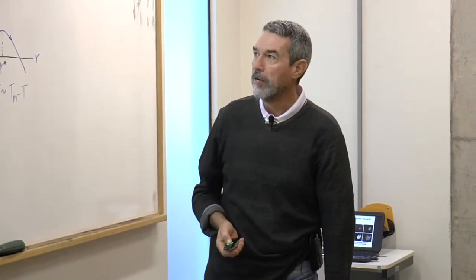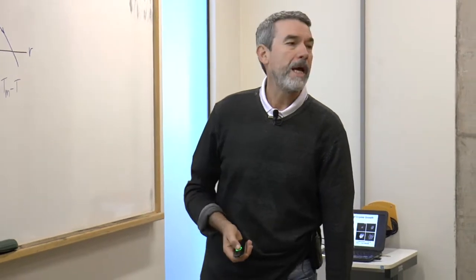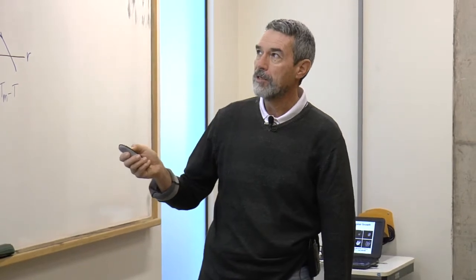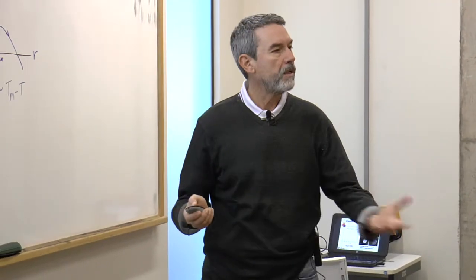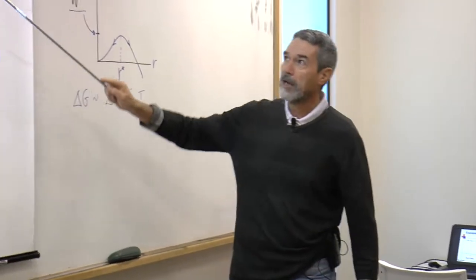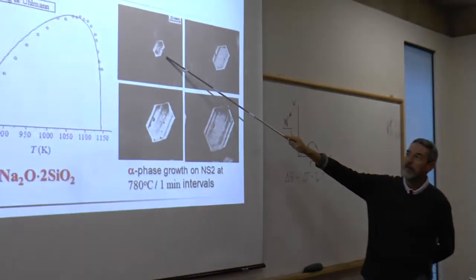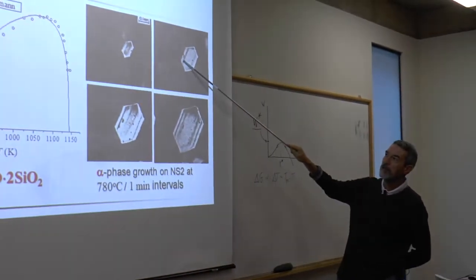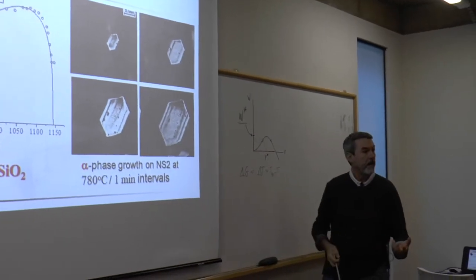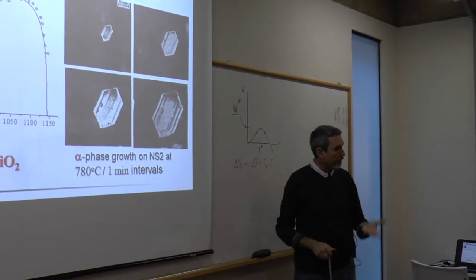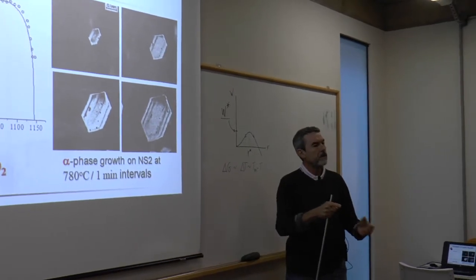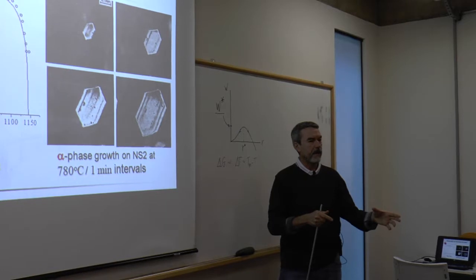Before we move into the theory, how do people measure growth rates? Well, you normally make a good glass, heat treat it properly, find a crystal in a microscope, and follow the size evolution of that one crystal as a function of time. If you have a heating stage microscope, you can heat in the microscope, pick one crystal, any crystal, and follow how its size increases with time.